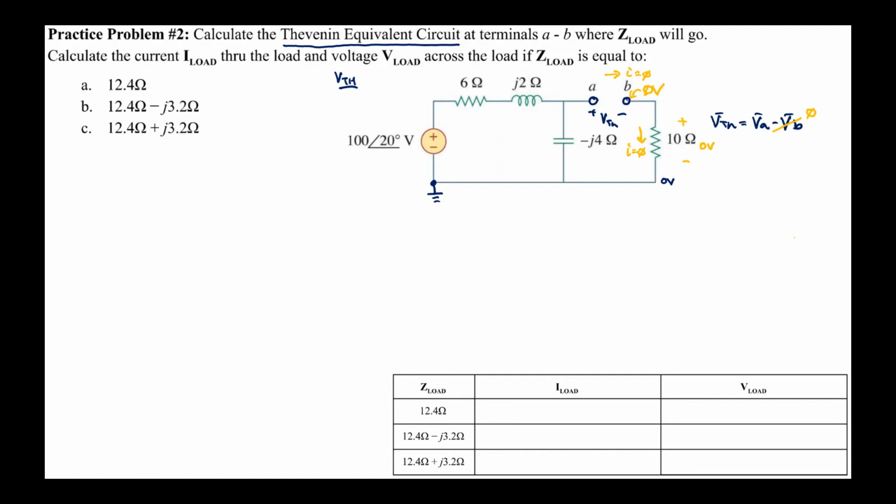It also means that the effective circuit, when solving for V Thevenin, does not include the 10 ohm resistor at all, because the 10 ohm resistor does not carry any current. That is, I can solve for VA with this series circuit. This is a perfect setup for the voltage divider approach again, and I use the voltage divider rule, which tells me that